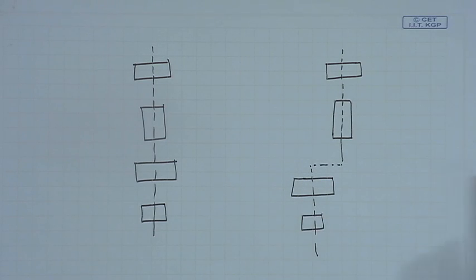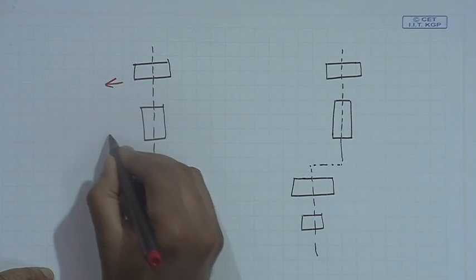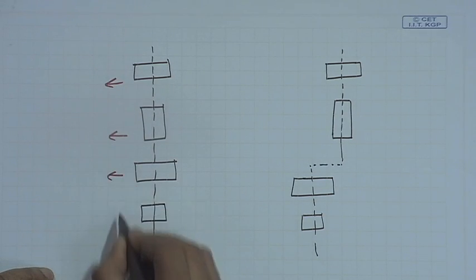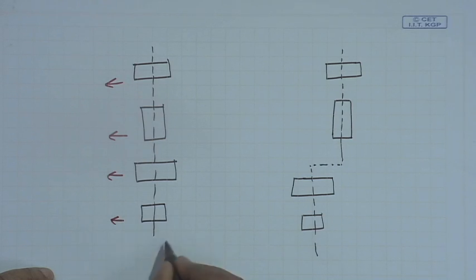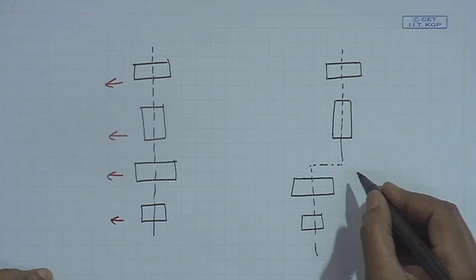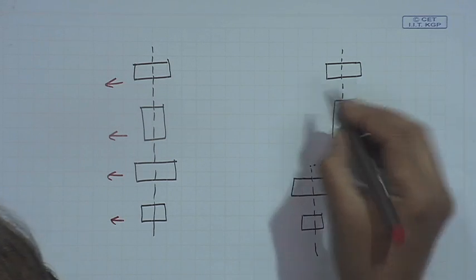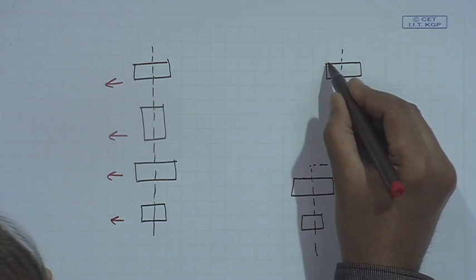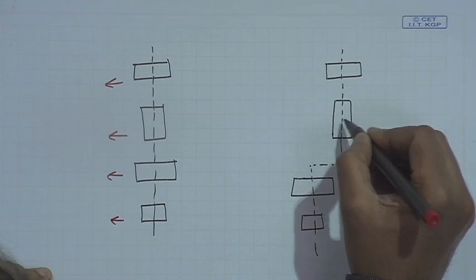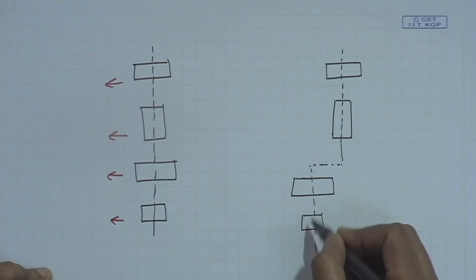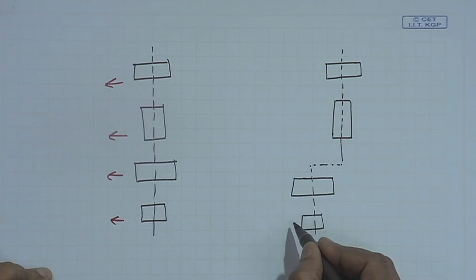So, in the earlier case for virtual grid compaction, I was shifting all these 4 blocks together as the grid was shifting, but now I am saying that maybe there are blocks to the left which are not allowing these 2 blocks to be shifted, but maybe these 2 features can be shifted.